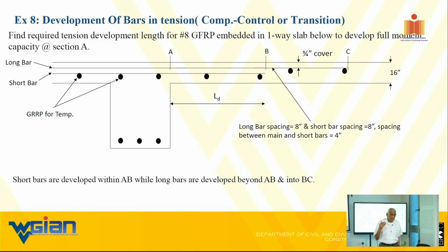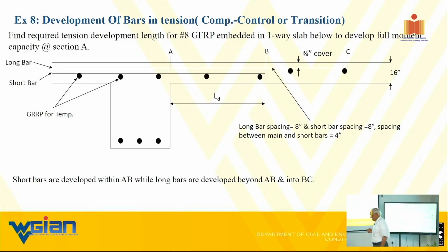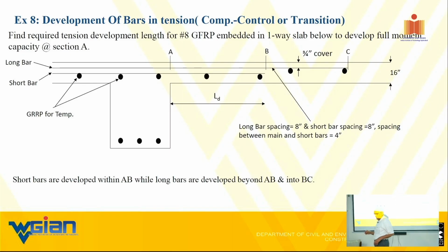But when strength is concerned, don't waste time and money with carbon. If you're strictly looking for an increase in strength, glass wrap will do the job. Strength increase, not the stiffness increase. Even with the glass wrap, there is an increase in stiffness, but not much.